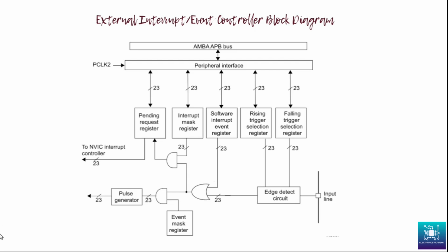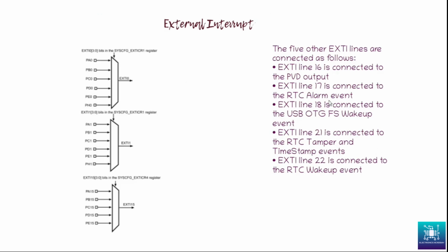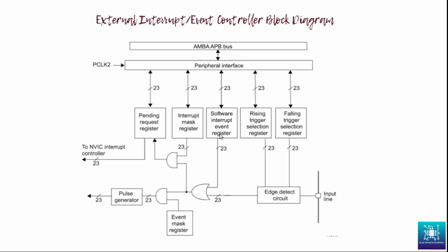Now, assuming that we want to raise a software interrupt. Software interrupts can be raised for interrupts and events. We saw in the previous slide that there are some EXTI interrupts where some EXTI lines are actually connected to certain peripherals.